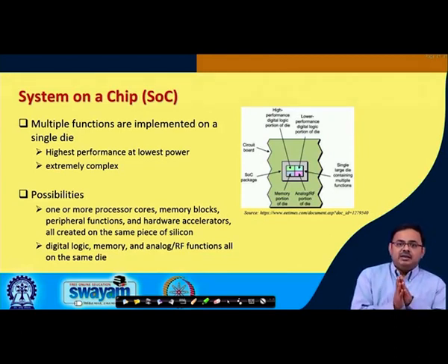But on the other hand, if you have, let us say, on-die memory, on-chip memory, then that is very different from processing. Now, that being said, there is static RAM actually on the CPU. When we talk about core and cache, cache is actually static RAM used for immediate storage of data. If you think of data storage, the first level is your cache, the next level is your dynamic RAM, DDR, and now of course you also have flash memory, and then finally your hard disk, right.